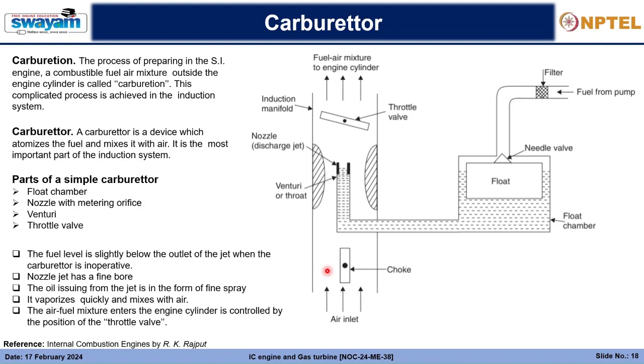As the ignition happens and it sustains, you will find that the engine keeps on running, and when the engine keeps on running, it gets heated up, you again adjust the choke valve, or you open the choke valve now, then the air gets inside the carburetor. So that's the fact you must have all experienced in real life.